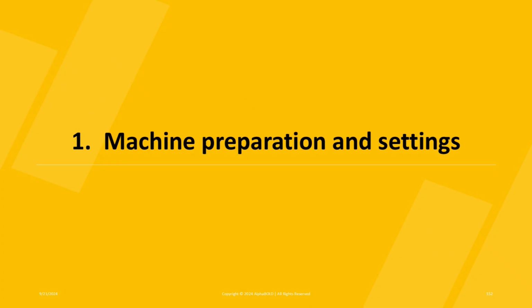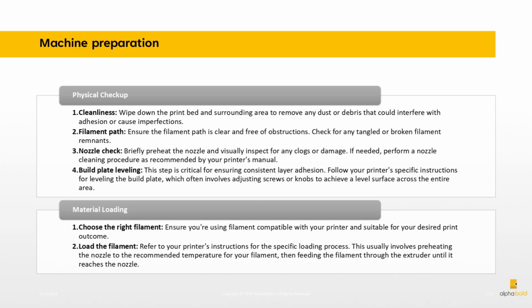Machine preparation and settings. Machine. Physical checkup. Cleanliness. Wipe down the print bed and surrounding area to remove any dust or debris that could interfere with adhesion or cause imperfections.